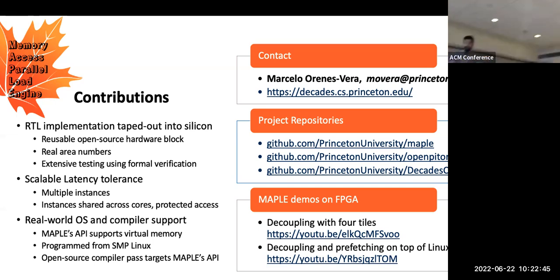Right. So the MMU has full support, so it has its own TLB and page table walker, and can even support page faults, which we implemented with an interrupt. It could invoke our device driver, so it would support invoking Linux to update the page table, and also supports shootdowns for making sure that if there is a remapping of the page table, things are kept coherent. Okay, thanks.